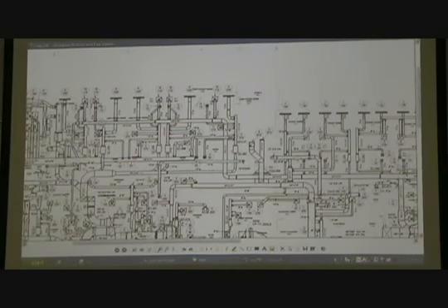All this return duct they would build as low pressure. Gauge and the reinforcement would be such that it's probably about 1/2 inch to 1 inch pressure. Straight fittings coming off of it, going to bath or to the rooms.